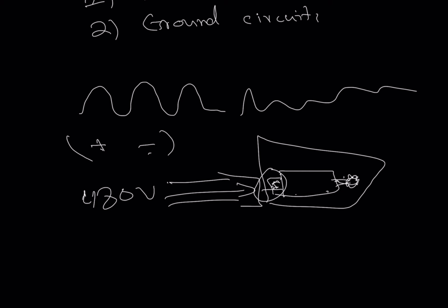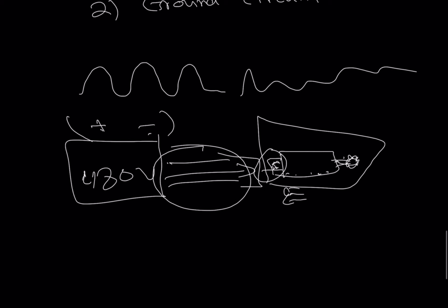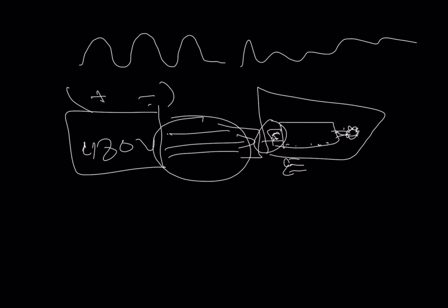Use the Megohmmeter or Megger to meg the motor. Check all three phases, this to that, to see if you're reading okay. If you're reading okay, then you must have a power source issue coming from the main panel. So that's how we use the Megger to measure the short and grounded circuit. For the short, we check in between lines.